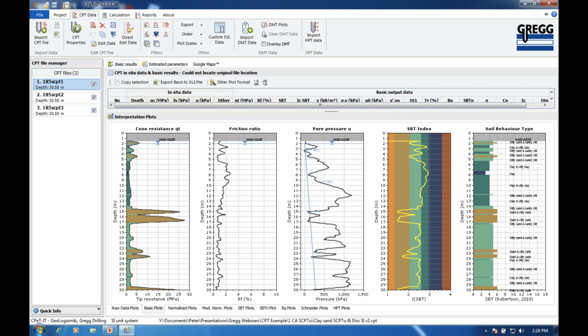So yes. Next question, is CN cutoff automatically applied to slick? Yes and no. Slick is a liquefaction program, and a lot of the methods have a CN cutoff, and usually it's 1.7. And so if you selected a method, yes, it automatically applies it. But if you go into the advanced parameter tab, you can unselect it. You can forcefully say, no, I want to see what would happen if I took it off. And of course, it usually only influences the upper couple of meters of data where the effective stress gets very low. And so you can toggle with it on or off and see what the effect is.